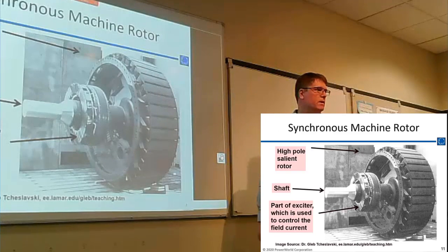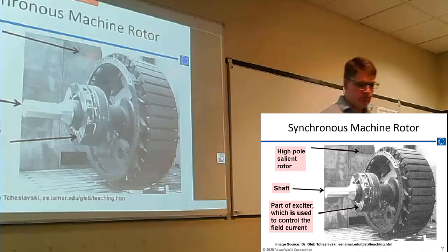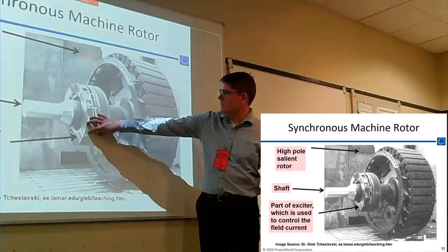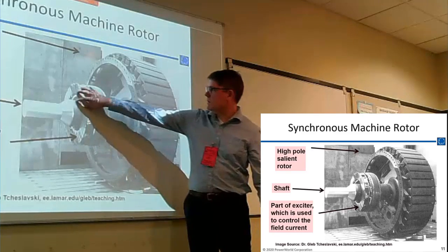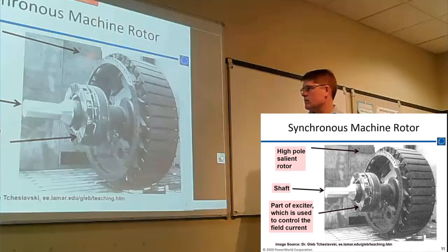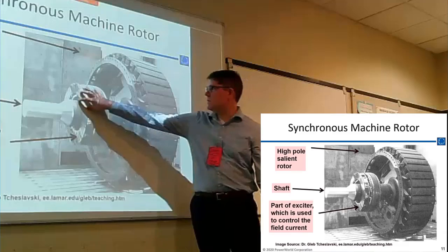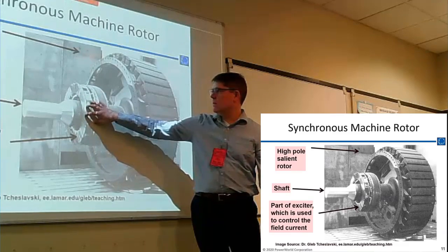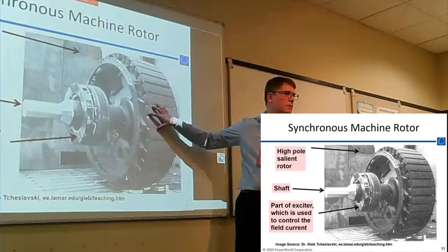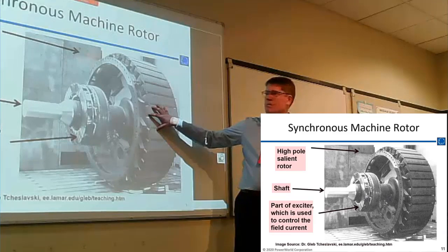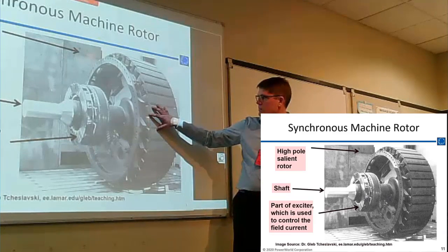It looks like it has an exciter. This, I think, is meant to be the exciter, a DC one of some sort. So it's old, it might have an integrated exciter. Yeah, so guessing this is creating the DC voltage which is being applied to this rotor. And then you can see the amortisseur winding on the very end there. It doesn't show up very prominently.